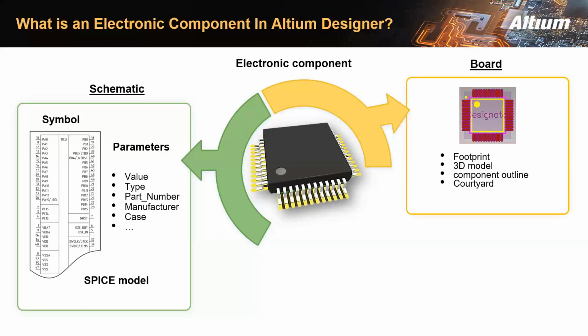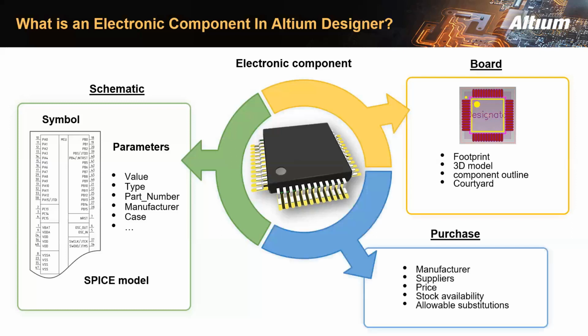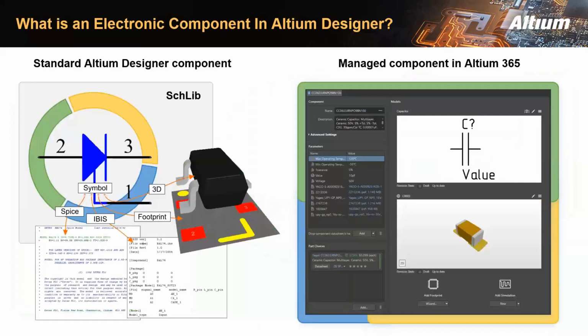Throughout all design stages, an important aspect of the component is its availability and cost. Part procurement can occur anytime after completion and approval of the schematic design and move in parallel with board design. For procurement, the name of the component and the manufacturer are important. Also, you need to know which supplier sells them, what their cost is, whether they have them in stock, and whether they are still in production or not. The component impacts many aspects of the design.